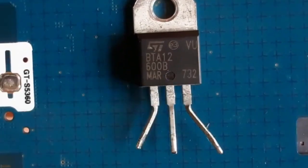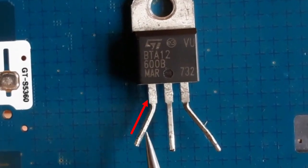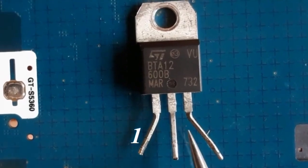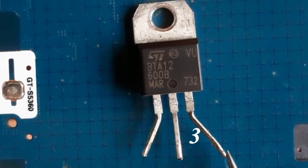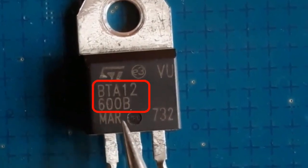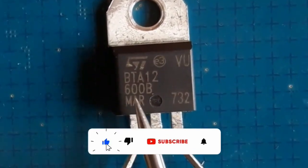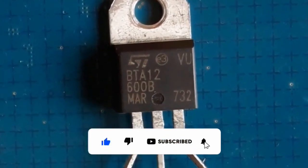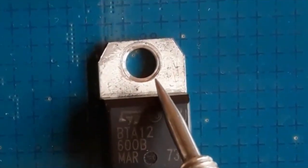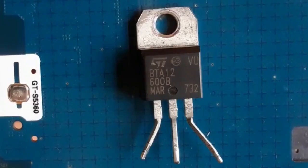As you can see here, we have a TRIAC. Of course, it has 3 pins or 3 terminals. So this is pin number 1, pin number 2, and pin number 3. Here we have the reference or the part number for the TRIAC, BTA12600B. If you have a bad TRIAC with this reference, you should replace it with the same reference, of course. Here, this part is used to connect the TRIAC with the heatsink because the TRIAC gets hot when working.